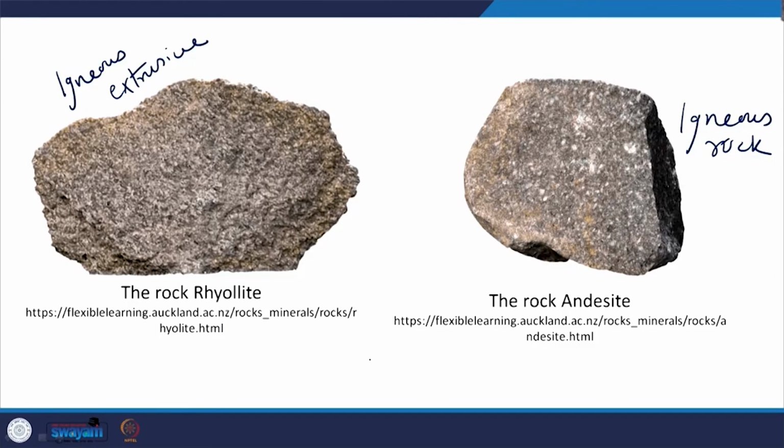Color is variable, but typically bluish gray or gray. The mineral this rock is made up of is pyroxene. Silica content is 52 to 63%, and it can be used as aggregate, fill, etc. in the construction and highway industry. Often it is not ideal for concrete aggregate because of the high silica content.